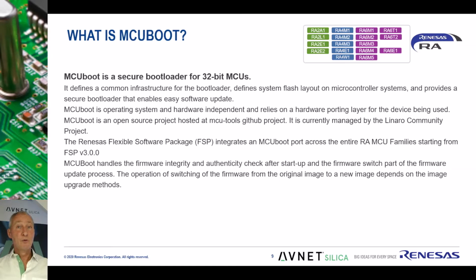So what is MCU Boot? Well, MCU Boot is a secure bootloader for 32-bit MCUs. It defines a common infrastructure for the bootloader and defines system flash layout of microcontroller systems and provides a secure bootloader that enables easy software update. MCU Boot is operating system and hardware independent and relies on a hardware porting layer for the device being used. MCU Boot is an open source project hosted at MCU Tools GitHub project and is currently managed by the Linaro community project.